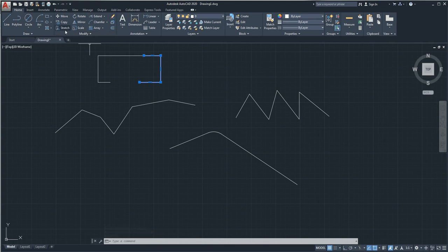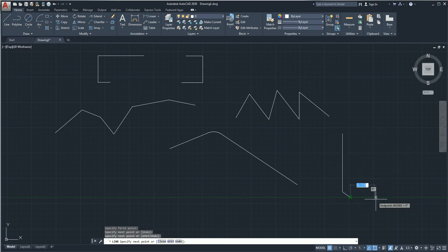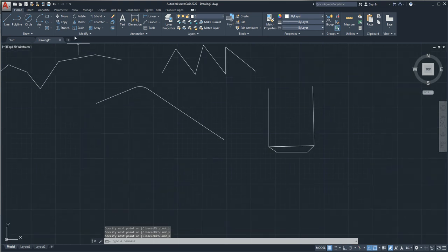Okay, let's move with the stretch feature. So let's click on this one. This will be the base point, and we can just drag it. Let's assume we have something like the end of the bolt. We have a chamfer right there, and we want to stretch it down. We can just click on stretch, select objects, those ones, base point, this one, and just drag it down. So this is a stretch. You make something like an elongation feature right there.